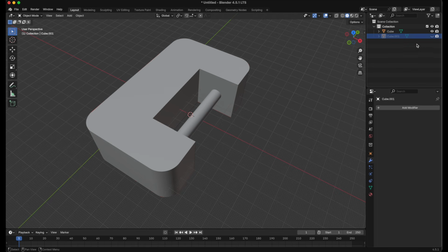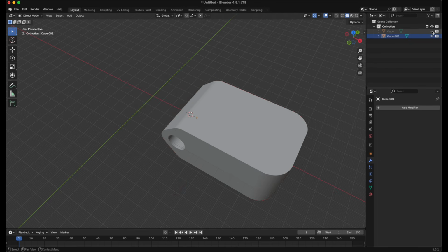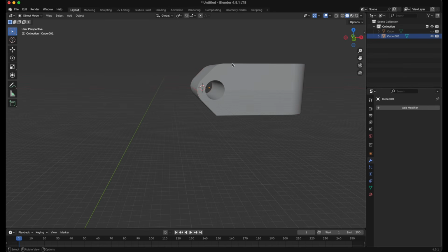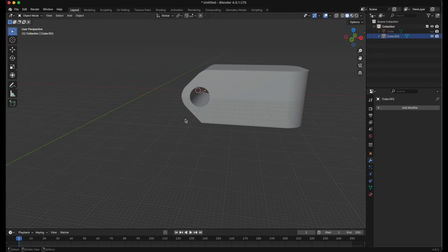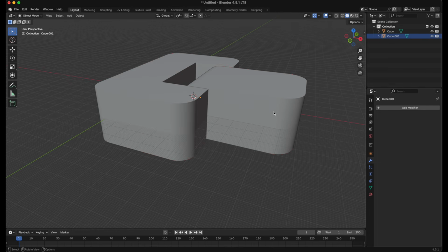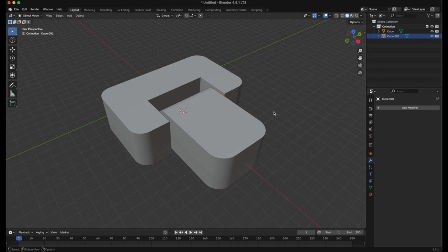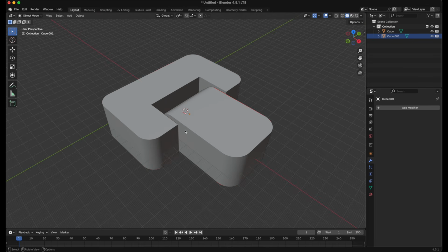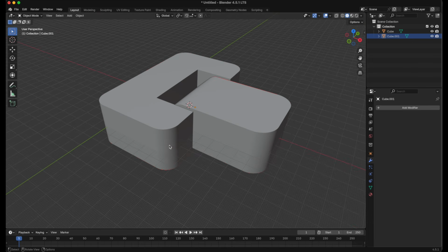And then we design another part here. I'll hide this one. It's just a simple part with a chamfer, some fillets around it, and the axle prints through it. So in this orientation, this could easily be printed and it will be print in place. And because the axle is printed horizontally with bridging, it's actually stronger than you might think because there's no layer line weakness. So this is just one method that you could use to create print in place parts using Blender.